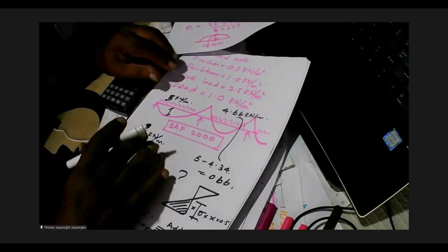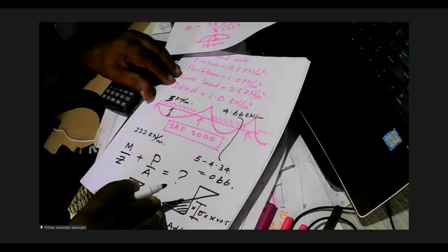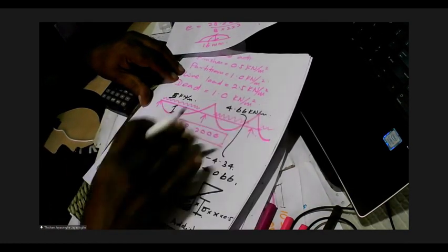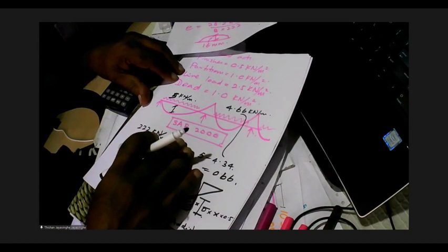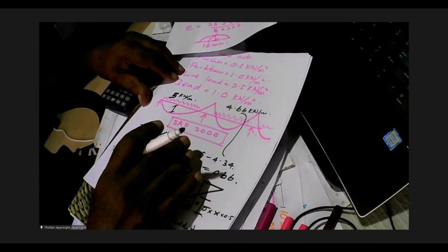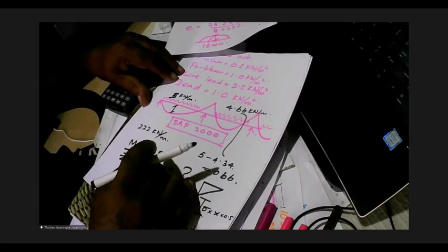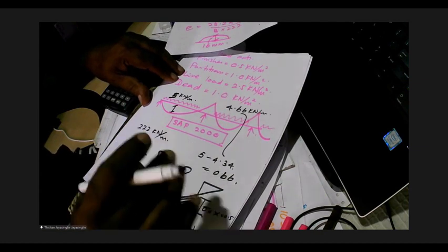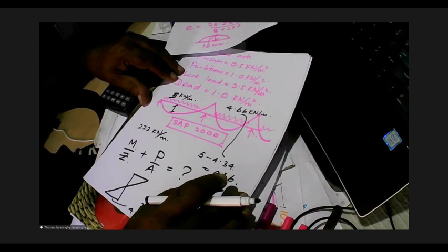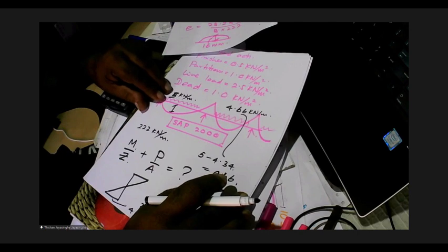What we do is we can apply the loads, the live loads, and then get a bending moment diagram. From that bending moment and the pre-stress that is available, you can work out the stress range. If the stresses are too much, then you can provide some reinforcement. If the stresses are within the limits, you don't have to do anything. The slab will behave well.